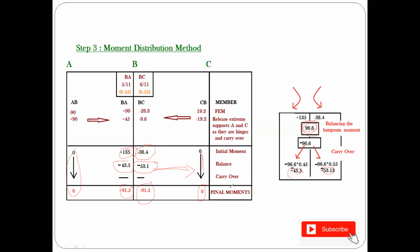So I'll again clarify that portion. That is, make sure if your net moment in the joint is positive, to balance it, you have to put negative. If your net lump sum moment is negative, to balance it, you have to put a positive sign. And that is how you are getting this negative 43 and negative 53.